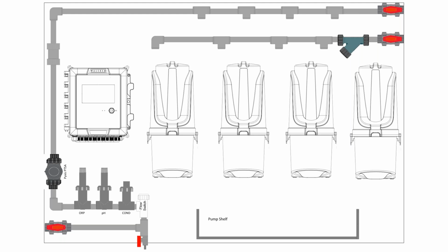Yes, that's correct. You also have exposure to the halogen, so high halogen levels. You've got total suspended solids. You've got all those other variables and wildcards that are out there in the cycled tower water or stressed water source. Well water we've used extensively on these dissolvers, 500 ppm total hardness, things like that.